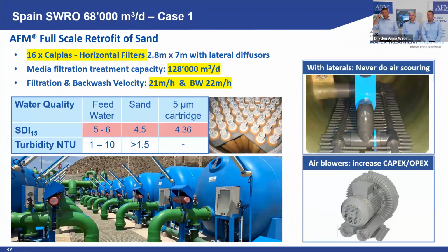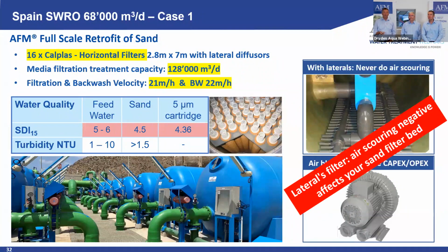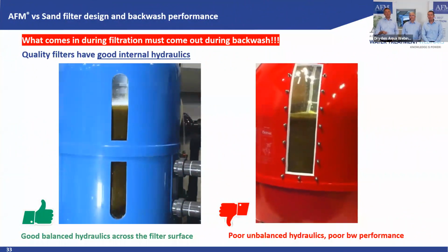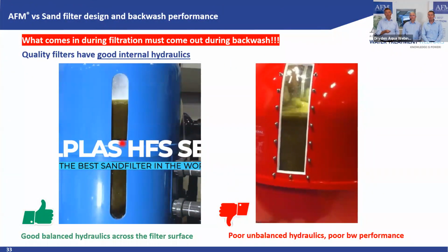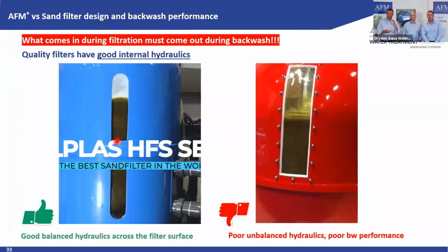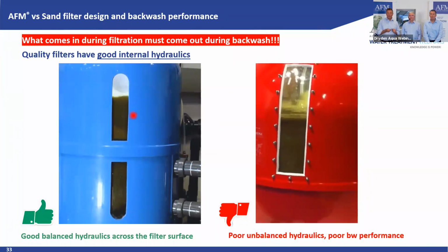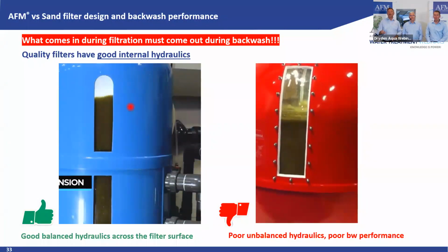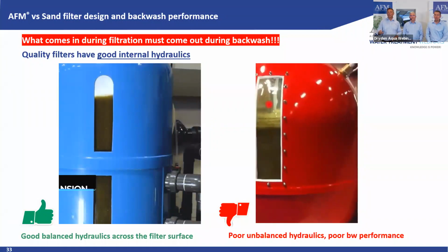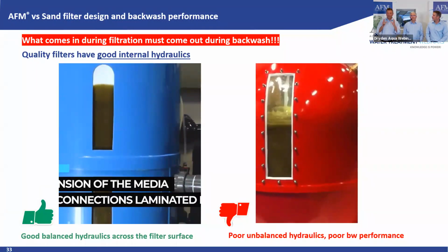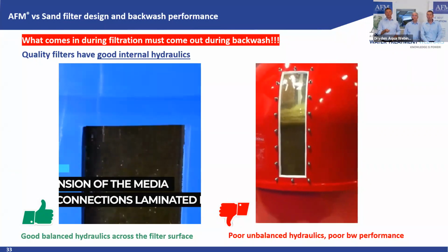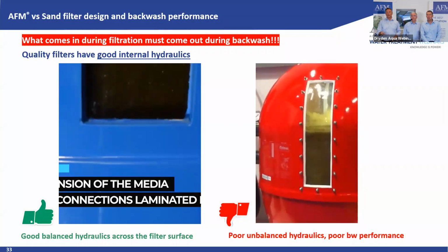And maybe you say, this guy is stupid and he's wrong and he doesn't know, he's only a pool guy. You're right, I'm only a pool guy. But I can preview this. These are two filters. One again is my friend from Colplus, very good. And this is in a backwash mode. This is not with air, this is just with water. And here you see it's backwashing down to the end because they have a perfect lateral configuration. And here you see it's only backwashing in the middle. Now remember, this is with water. If you would have air, also these Colplus filters would look exactly like this, even worse.